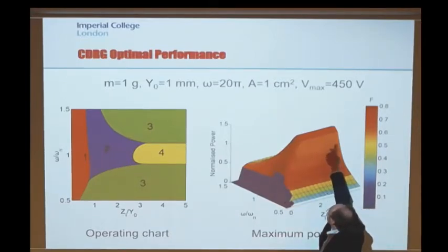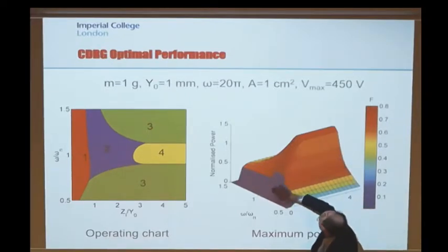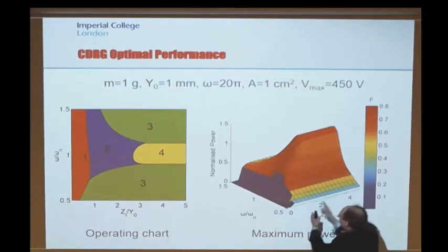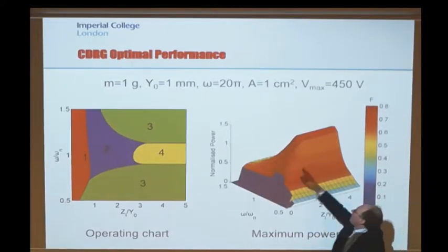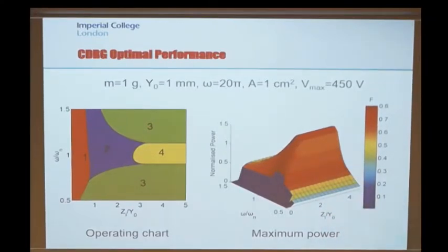We've also got a limitation here where we can't generate any more power, where basically we get a flat top on here. So you can see that you get some benefit here from operating at resonance once the device gets fairly big. But ultimately, as it keeps getting bigger and bigger, it doesn't help us. And the reason for that is, from a practical perspective, we reach a point where the voltages that are involved in producing more power as we make the device bigger get higher and higher because we've got more movement. As we have more movement on these parallel plate capacitors, that requires more voltage, and eventually you reach the point where you can't support that voltage because your transistors are not able to support it.